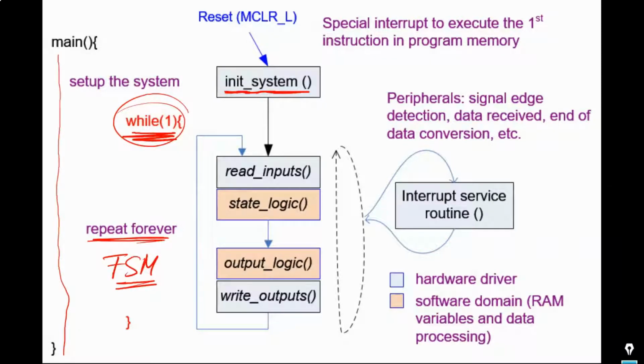This is what is going to be repeated all the time, the same way, at the highest speed possible. So read inputs to get level sensitive inputs. Okay, you have some pins that are level sensitive inputs like night mode or up and down or count enable.